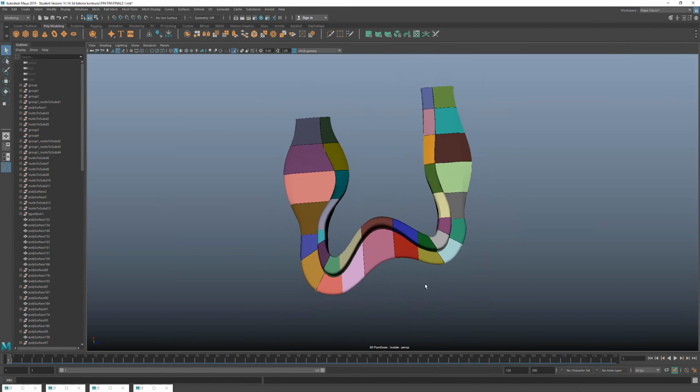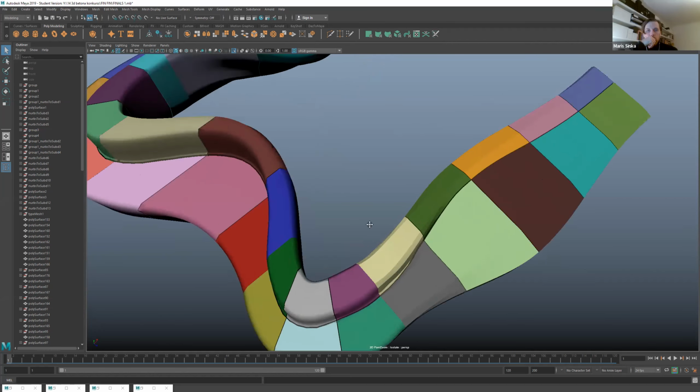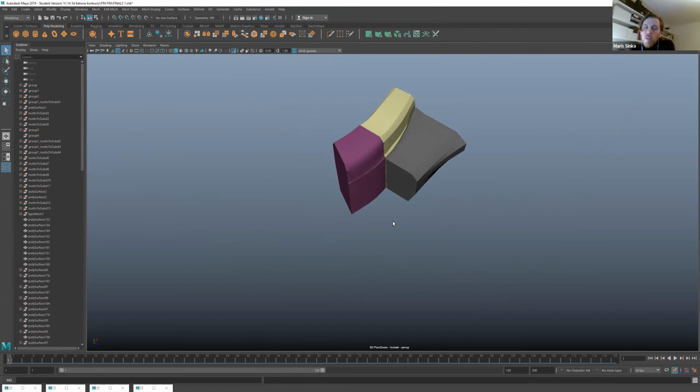I would suggest to test like 4 parts, to test out also the connection. For example, here are those flower pots, and they will be printed in different directions, and maybe it would be better to test one of those flower pot parts and 2 of those, like those 3 or 4 parts, and test out connection angles and how it looks, something like that.